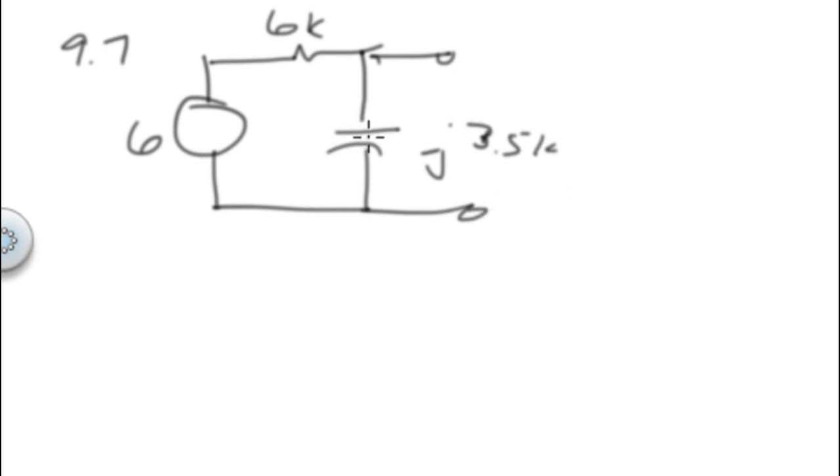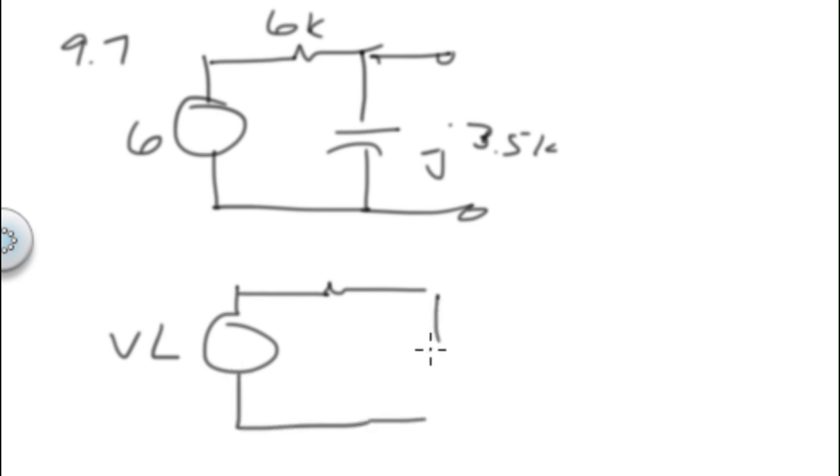Thevenize this part, and then from there reconstruct it with a voltage, and this voltage will have a phase. It will be a voltage at an angle, with a complex resistance, and then you stick the L back in and you can find the I very easily.